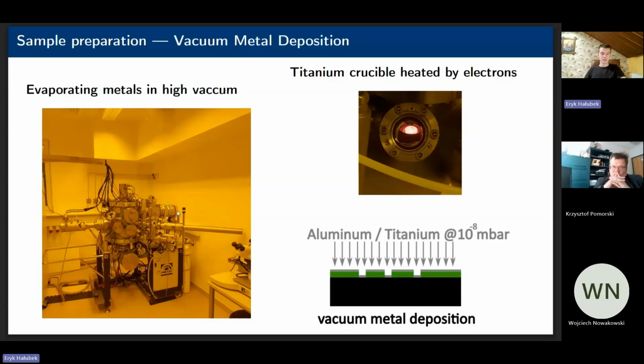And the main chamber has its own vacuum pump, the turbomolecular pump, slightly bigger here. And these pumps are really crazy because they rotate at speeds of about 1,000 rotations per second.